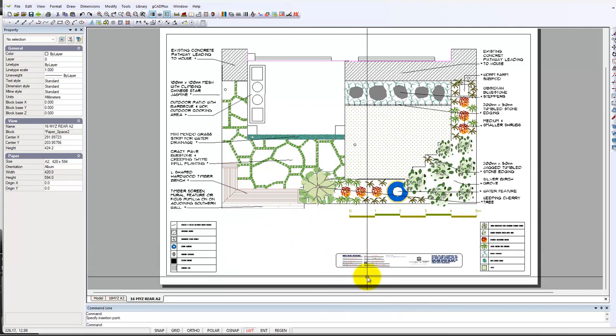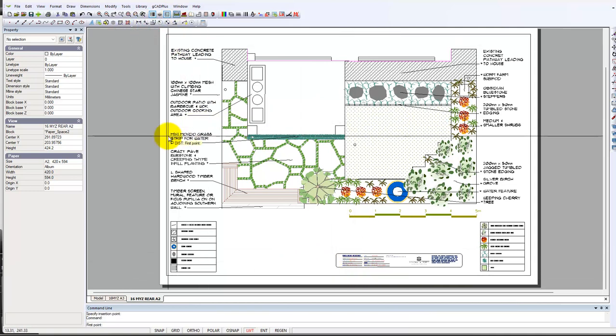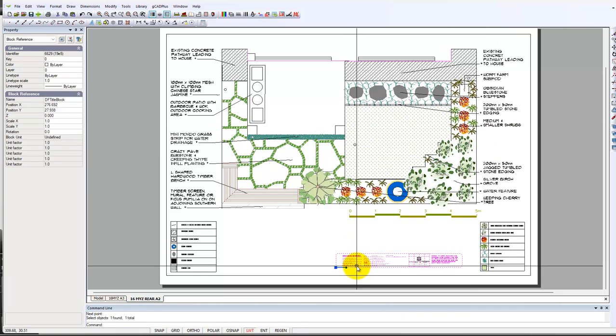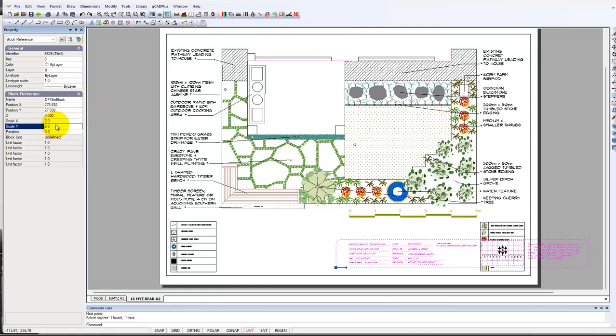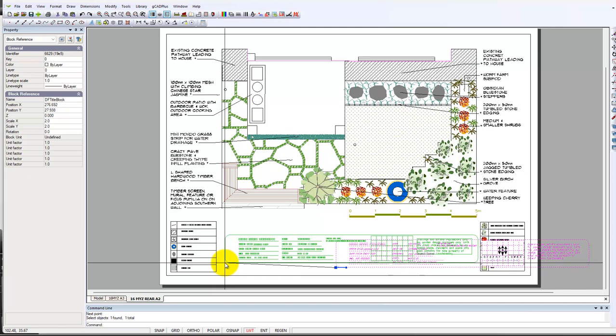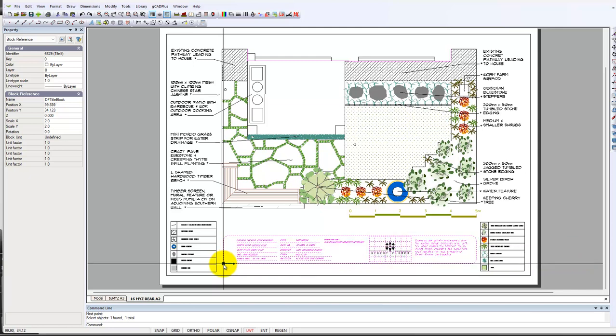Now that worked well at 200 millimeters long, but remember that a sheet such as this is 540 millimeters long, so we can just scale it now. Scale 1, we will double it and double it again, and then we've got a base point down here and pop it into position.